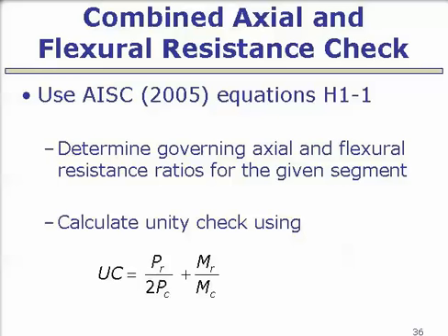That's just the particular one that we're going to be hitting here, and often we'll hit. We're in a low axial load range, and so we're just focusing on this particular form. There is the other form of the beam-column interaction equation that applies if you have higher axial load. Okay, so let's suppose we're going to do the beam-column check for one of our exterior columns here.